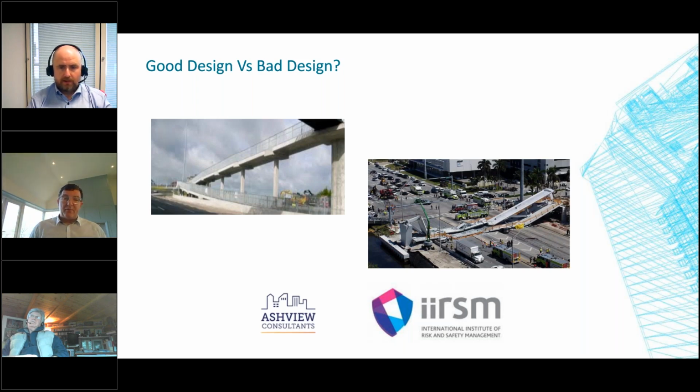So obviously a lot of planning went into the off-site part, a lot of collaboration, specialist input from the precast guys on the sequencing, the size of the panels, the size of the crane, the locations of the crane, less movement. So looking at design risk management for us on that particular instance was about bringing the permanent works designers, the specialist designers, the schedulers, the planners, the crane guys in to tell us what size of crane. So that whole collaborative approach to design risk management and ensuring that, as much as we've got to build these objects, we've got to build the pedestrian bridges, although we're looking at the design part, what's the constructability of it and the future maintenance as well.